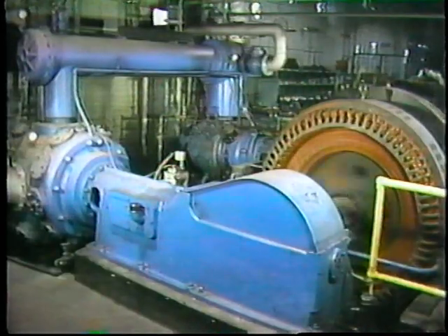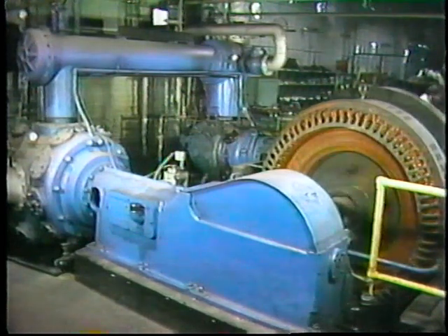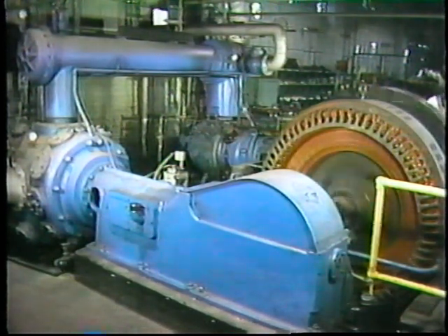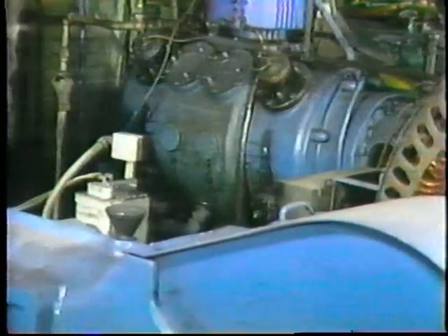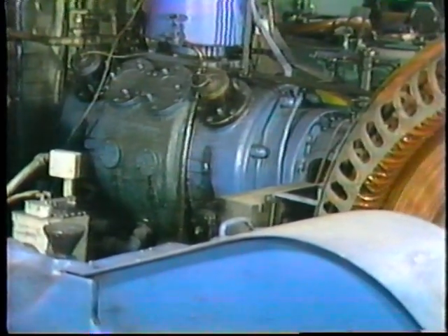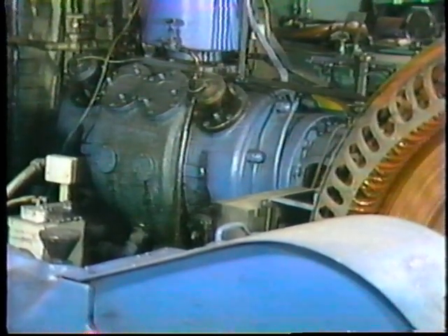As we explained in Chapter 3, the energy delivered by a compressor is not used immediately, but is stored as potential energy in an air receiver tank. The system receives compressed air from this tank in order to perform work. And of course, the pressurized air must be replaced. That's the job of the compressor, like the one shown here. You'll find that in most applications, a compressor is designed into a system so that it operates on an intermittent basis. When the compressor is running, it delivers compressed air to the tank until a specified pressure is reached. Then it automatically shuts down.